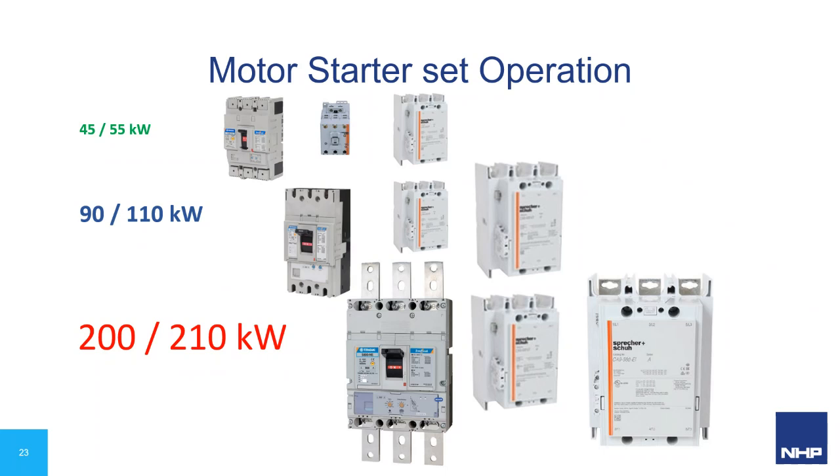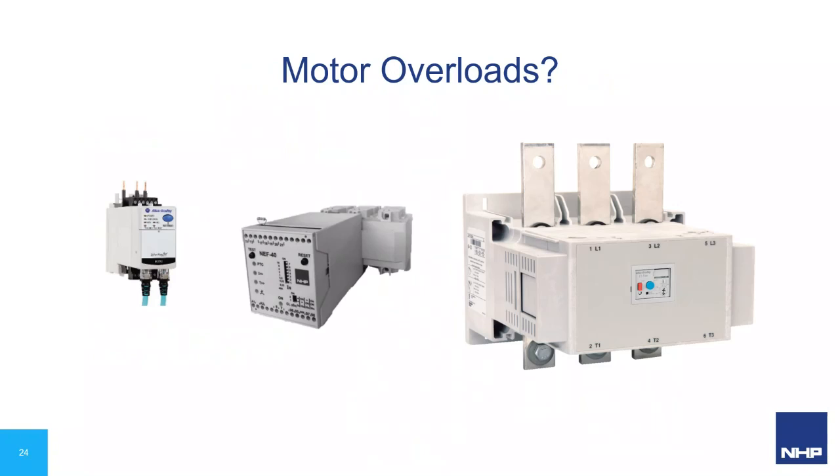So, do we have to upgrade the motor overload protection? Well, this is going to depend upon a number of factors. Number one, if the motor circuit tripped later than about 2 seconds after the start was called for and it tripped the overload, the most probable cause would be that the motor continued to draw close to locked rotor current for too great a time.